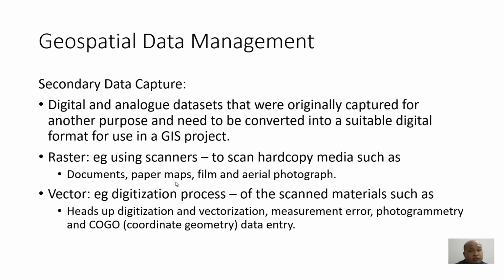How about the vector? Vector requires a digitization process of the scanned materials. So after we have converted the hard copy media into digital form, we can start with the digitization, or the tracing process. Let's say we have an aerial photograph that we already scanned.